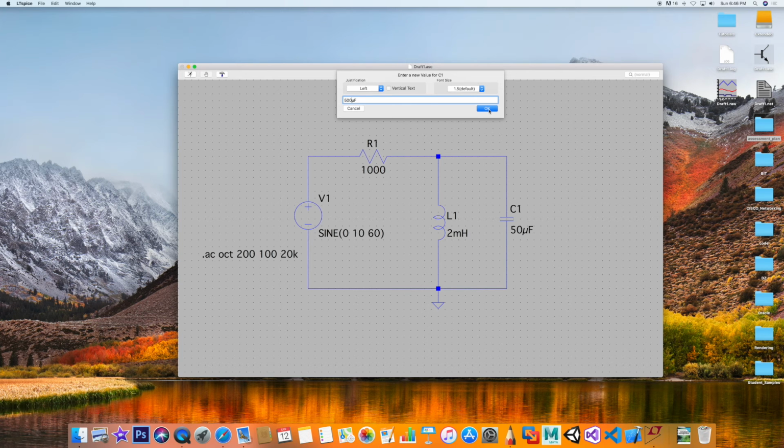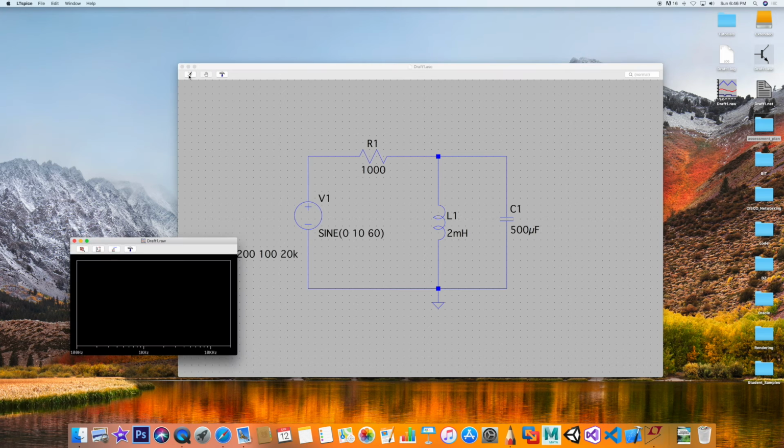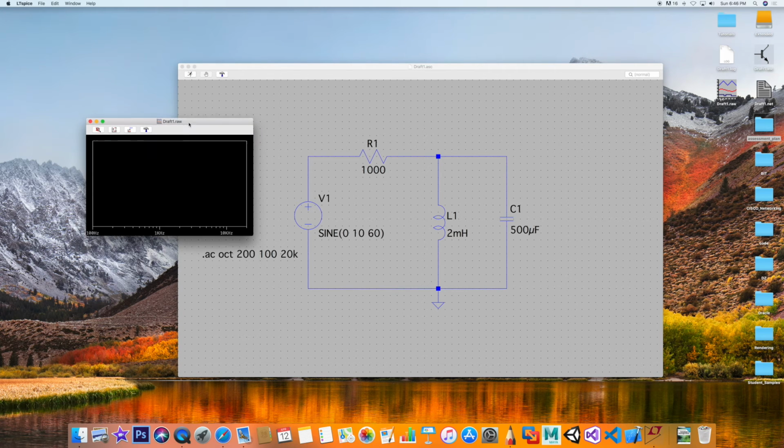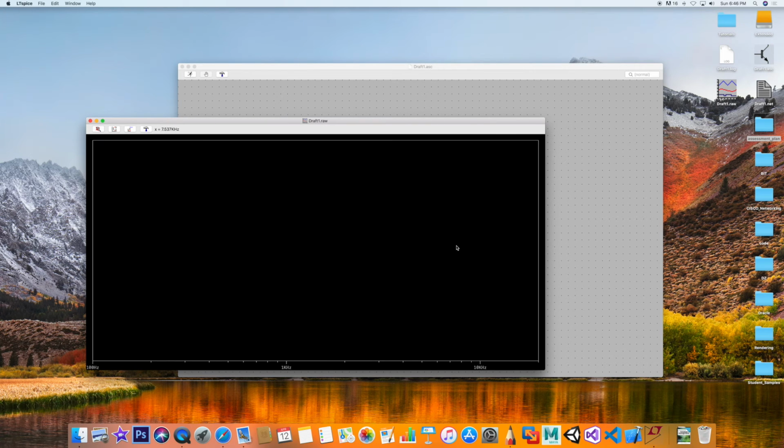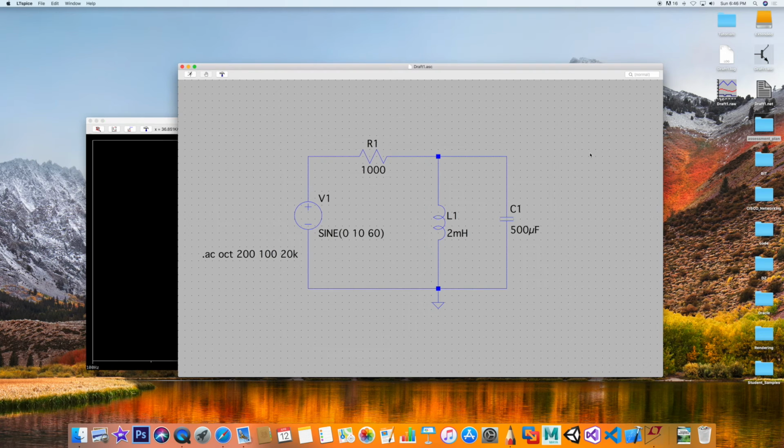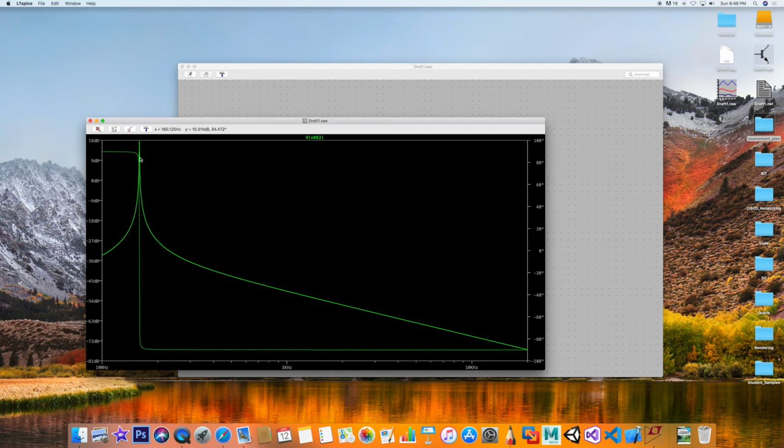And then we're going to go the other way. So let's go ahead and play with this. The capacitor is typically what we would find in a radio that you can modify. When you're turning that knob, let's see what happens here. Voila, it's shifting right here. Right, because as we're increasing C, X of C is decreasing. So it's becoming more and more inductive.